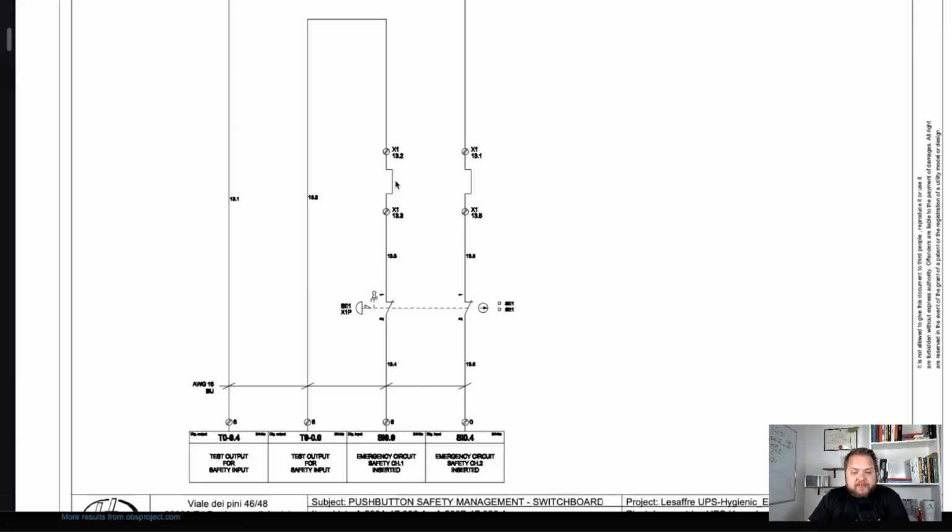And so what is an example of this something else? Well, the example could be you have a machine that's part of a line where the e-stop needs to be located maybe at the start of the line but also at the end of the line in a common safety stop circuit. So this is not going to be one of those applications where you hit the e-stop at one machine, then you have to run to the next one to hit the e-stop, to the next one, to the next one. Maybe you want to make this part of a chain, and so this is where you would insert some of those contacts. And so if any of those contacts are broken, this machine is going to be basically e-stopped.